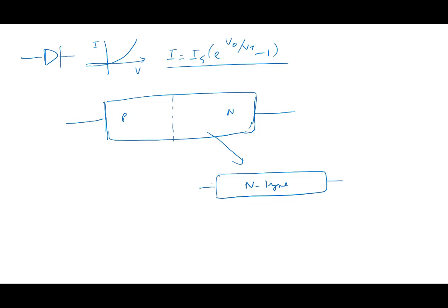Now, when I take an N-type semiconductor, what do I mean by that? N-type means I've added dopants, right? If I've added some impurity which acts as a dopant, what this impurity does is make n greater than p, in fact normally much larger than p.